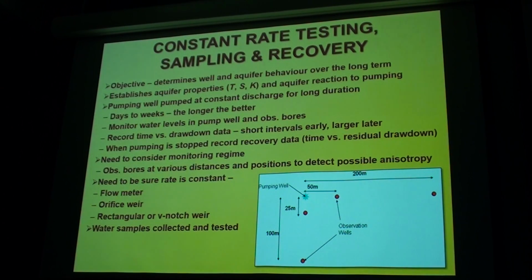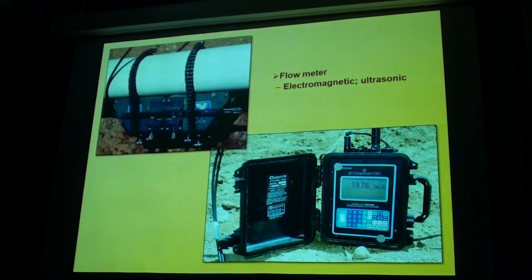Water samples will be collected during the pump testing, preferably early on, maybe a few hours to a day after you turn the pumps on. It'd be nice to get some in the middle, but definitely just before you turn the pump off. Then you'll be able to see some trends, decreasing trends or increasing trends, and nasties that you've discovered or whatever. But you've got to make sure that the water is acceptable, and if there are issues with it, they'll go to the client, because then they'll need to plan how to treat that water and get rid of those issues when they start using it for water supply.